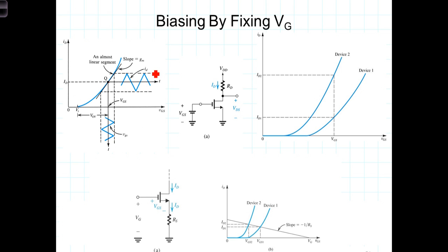So setting the bias point involves setting VGS, the voltage from the gate to the source, and the current through the transistor, and in the process we also establish the bias, or the quiescent, or the resting VDS. As we've derived, in saturation, ignoring the early effects while doing our DC calculations, I sub D, the drain current, is given by this equation that we're becoming pretty familiar with: 1/2 mu sub n COX, times the aspect ratio W over L, times (VGS minus VT) quantity squared.